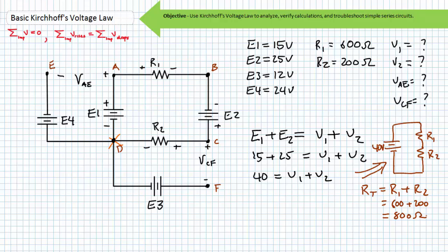In its most basic configuration, this single loop could be conceptualized as a single 40-volt source in a circuit with an 800 ohm resistor. I know this is not how our monstrosity is set up, but our KVL analysis allows us to make this simplification. We can now perform an easy Ohm's law analysis of this simple circuit as if this was true. The current through this idealized total resistance is the voltage divided by total resistance. 40 volts divided by 800 ohms yields a current of 50 milliamperes.